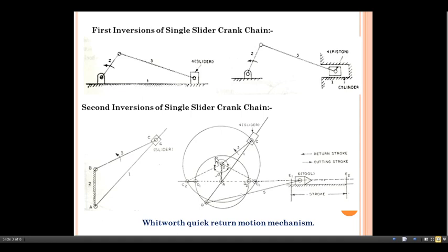It will take a longer time for its displacement, so automatically the time required for the cutting stroke is larger than the time required for the return stroke. So we can express a relation with the help of a mathematical formula, that is the time of the cutting stroke to the time of the return stroke.